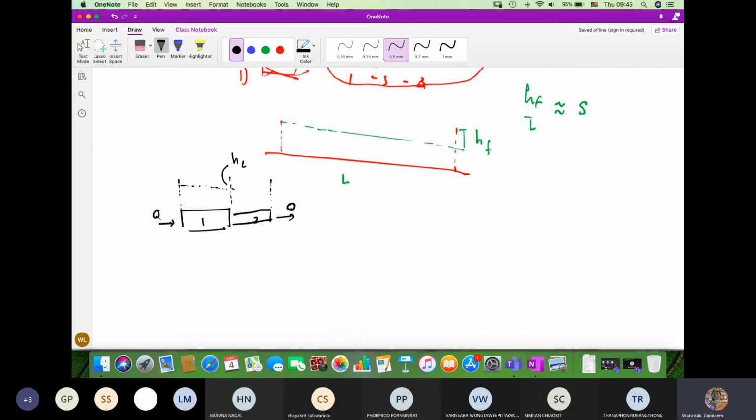And then the second pipe, while there is a flow, there is loss due to pipe number 2, like this. And if you still remember, according to the characteristic of pipes connected in series, you will find the total loss is equal to the summation of the loss in each pipe. So in this case, the loss in pipe number 1 combined with the loss in pipe number 2 will be equivalent to the total loss. So this is the first characteristic of pipes connected in series.